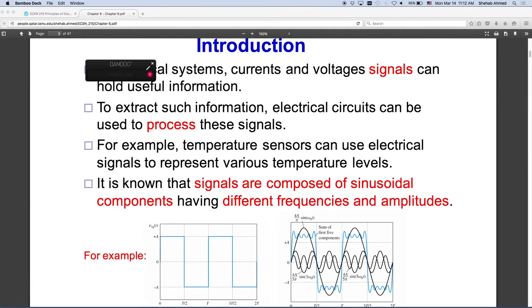You're looking at, for example, a temperature sensor that is basically a resistance. Temperature sensors are RTDs, resistive temperature sensors. They're basically a resistor. So sometimes you're measuring the voltage across the resistor, and that resistor, for example, you would put next to your system that is heating up, right? So you want to make sure that the output of the measurement circuit is a true replica of the temperature that you're measuring, right? But you have this resistor on there, and this resistor is going to go to a different circuit to do what? I mean, the resistor by itself doesn't do anything, right?